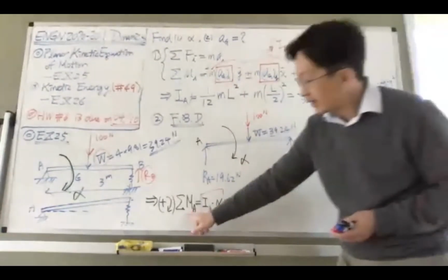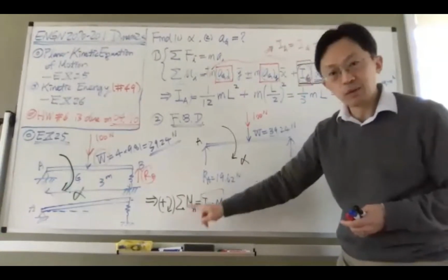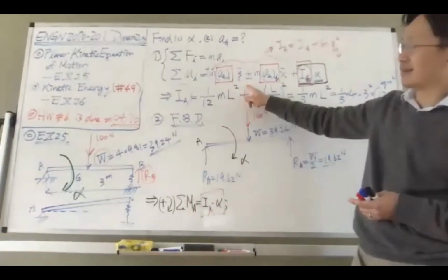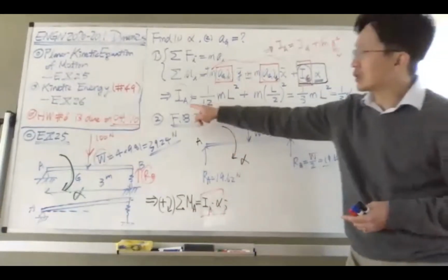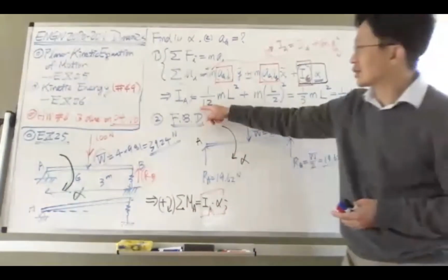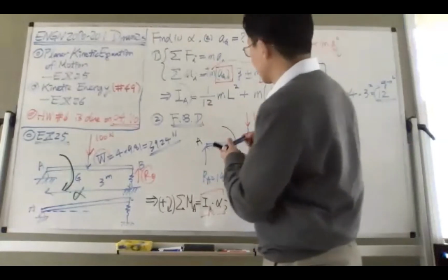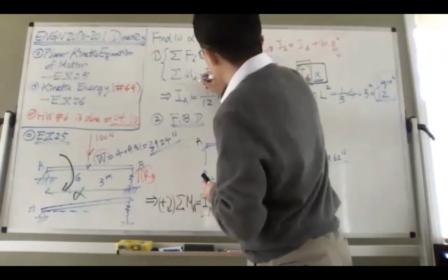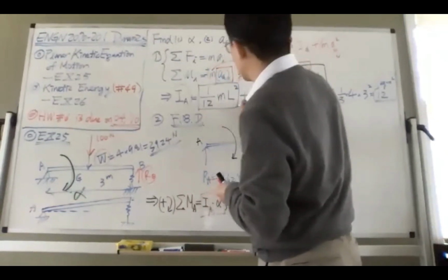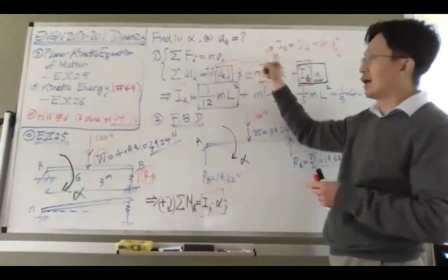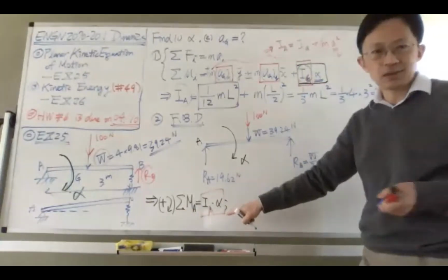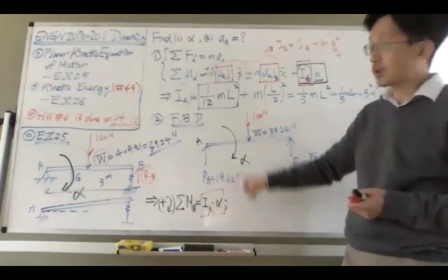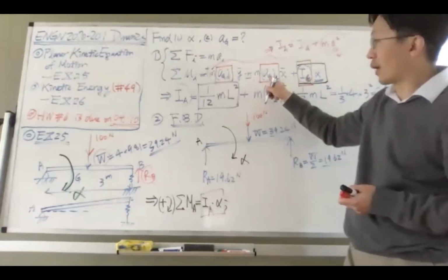Therefore, when we write down the moment equilibrium, you can choose to go this way. You say, I don't want to find out IA, I just want to use IG, which is just this one. This is IG here. But if you choose that, you will have to consider 3 terms on the right-hand side of the moment equilibrium, which may not be a good idea, right? Besides, we don't even know what AGX and AGY are. How can we use this?